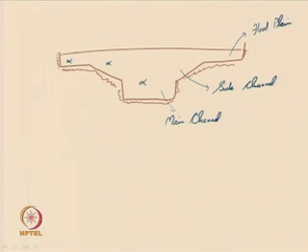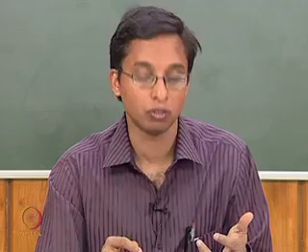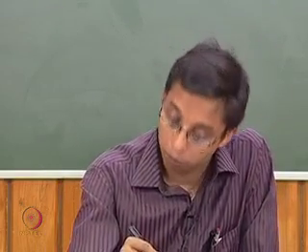So, the roughness of the location may be quite high and this may lead to a different type of energy correction coefficient. In the side channels, the water may be existing, but during flood it may be in a different way, and the main body is mostly always carrying water, so its energy correction coefficient may be quite different. So, you can have an individual energy correction coefficient for each of the sub areas.